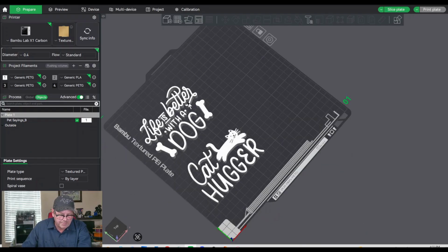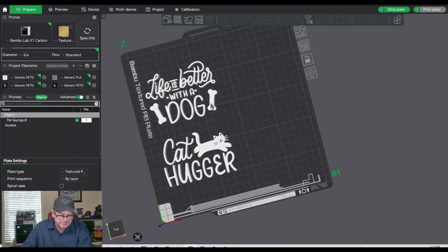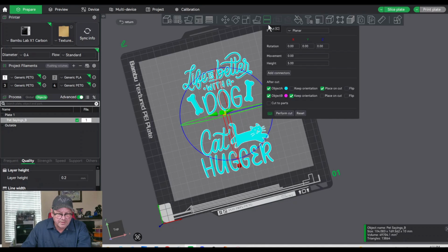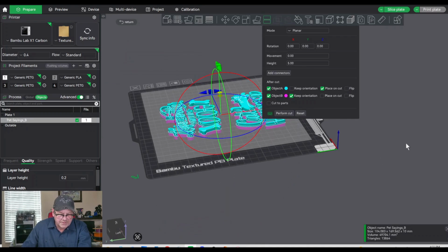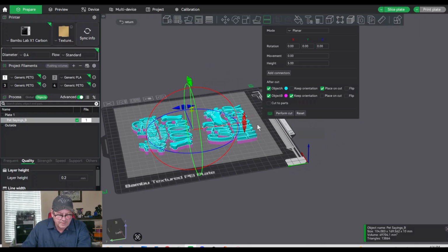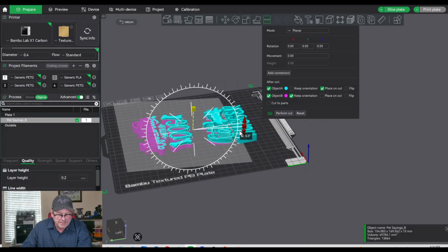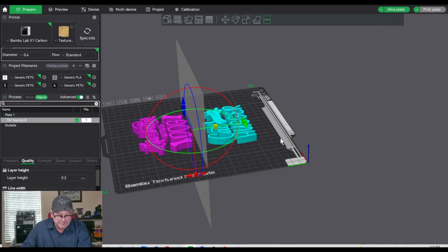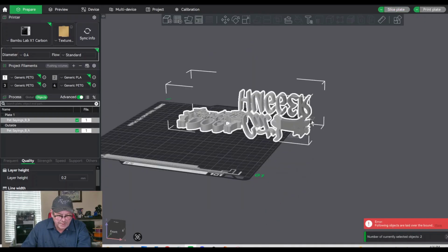So now I've got to cut the bottom piece off here. So I'm going to perform another cut. This time I'm going to do the same thing. I'm going to rotate the cutting plane 90 degrees. Remember to hover over the line, it'll snap. Now if I do it like 85, it's not going to matter because I'm not really cutting through any material. So I just, at 90 degrees, perform cut. And now I have 2 separate parts.